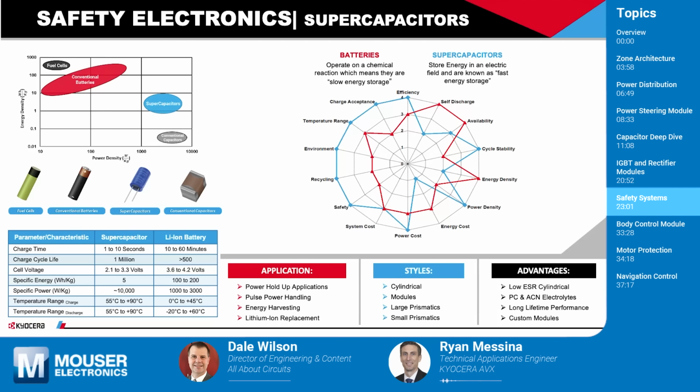Some novel approaches are you put a supercap in on that module down where the doors are. You have that burst of power that'll be able to unlock your door or roll a window down or whatever it might need to do. Supercaps, they can deliver that. They can deliver such high levels of current, they greatly eclipse batteries as a power source.